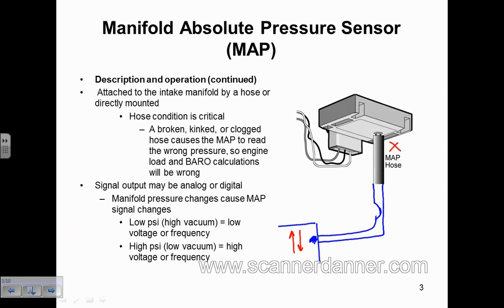So what's the computer not do? We don't have enough fuel, so do you understand why the car hesitates really bad? And then if you held the throttle there, it actually smoothed out after that. That makes sense too, because any trapped vacuum up in here would bleed out, right? Then we'd have the right pressure indication to the map.